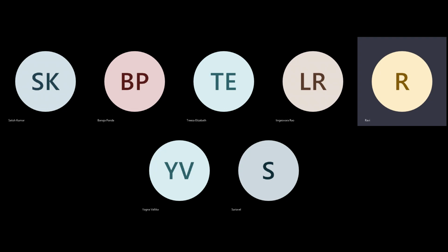Because around memory, when you are placing, you have to take care of the memory to memory rules: whatever spacing, you have to route it properly. Then if the blockages have to align, whether the memories have to face each other or be against each other, these are things you can take care of. You have to spend enough time on just memory placement.